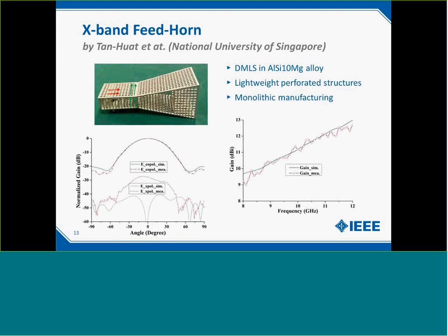The concept has been applied by the same group to an X-band feed horn. The perforation of the structure is performed in a different way in the vertical and in the horizontal walls. In vertical walls, we have some transversal vertical cuts because the currents, shown in green arrows, are transversal, whereas in the horizontal walls, the currents are both longitudinal, the red arrows, and transversal, the vertical ones.